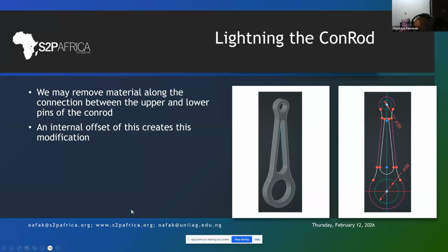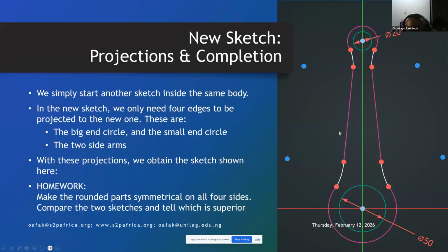So while you are here, you can do that arc here very easily. You do a 3-point arc, choose this point, and choose a point below. That will do you an arc. Same thing, 3-point arc here, and somewhere in the center will do you another one here.